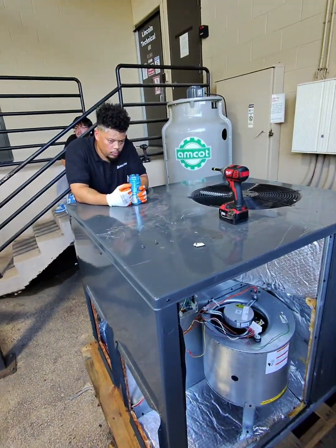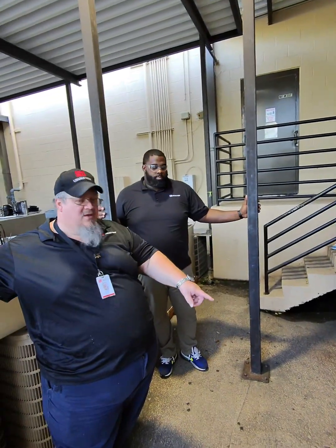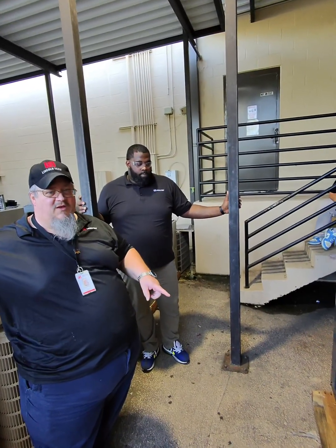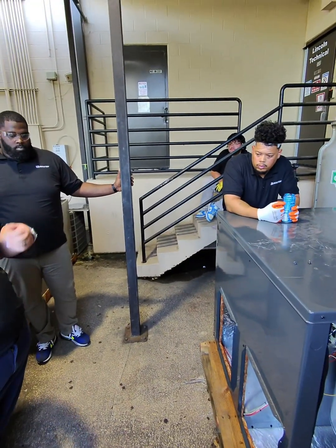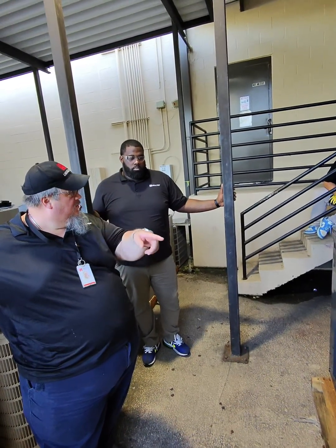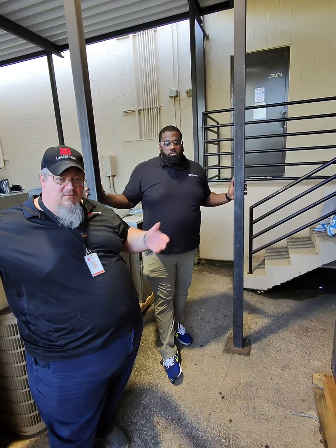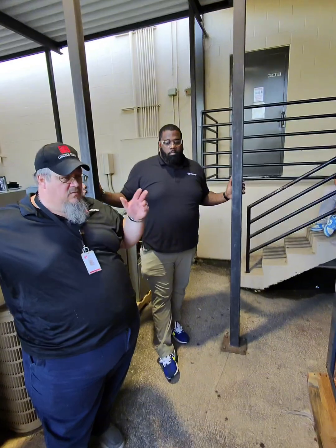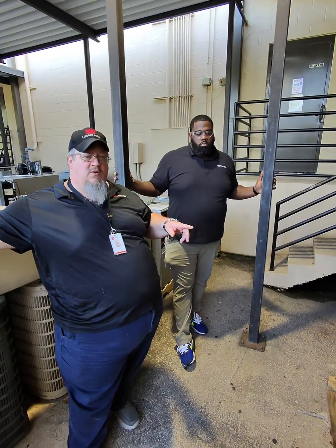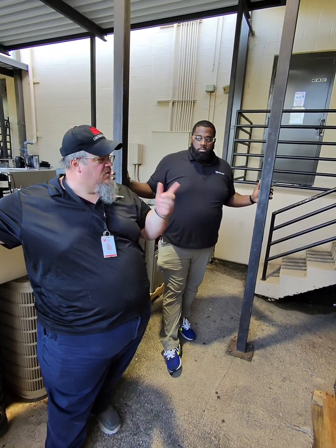You see what I'm saying? Because like air conditioning, you're going to see evaporators come in all different shapes and sizes. Does it do the same task? Absolutely. Same task. Are we still looking for superheat? Yes. Are we still checking for subcooling on our condenser? Yes. Absolutely. Is it going to be different levels? No, it's going to maintain the same. No matter what refrigerant you are working on, don't pay attention to pressure, convert it over to temperature, and maintain your superheat and your subcooling.